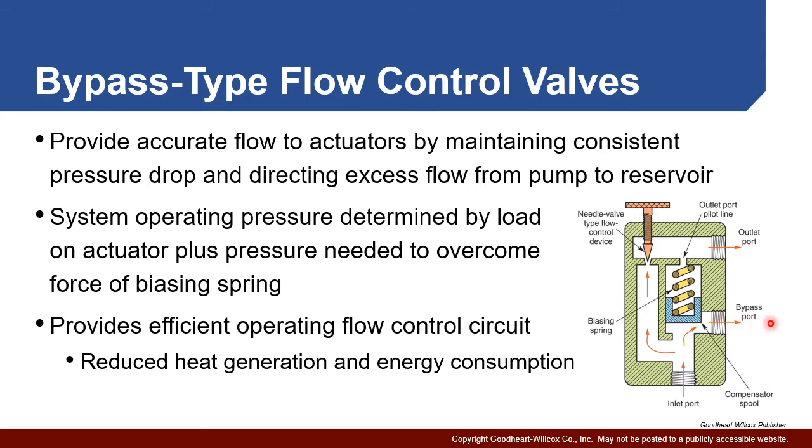The nice thing about that is we don't have big pressure increases. We don't have the fluid being forced through small orifices, and as a result, you're not going to have as much heat generated. It's going to be more efficient in the overall function. So a little bit more complicated device, but it has the long-term benefits of that reduced heat generated.